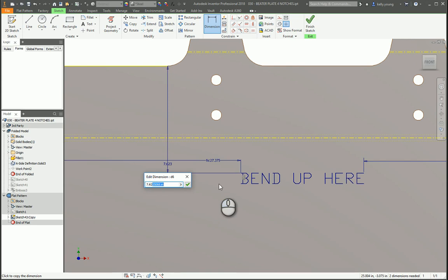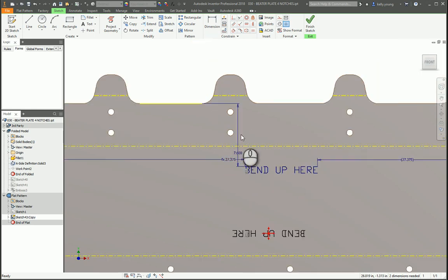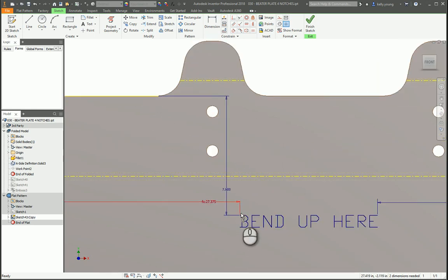And I'm a big fan of not using dimensions like that, so make them as easy as you can. So that way, if a guy's actually going to measure it on where to put it, you can measure it accurately rather than saying it's 27 3/8 over, rather than saying it's 27.42, because there's no way to measure it and you can't hold anybody accountable.